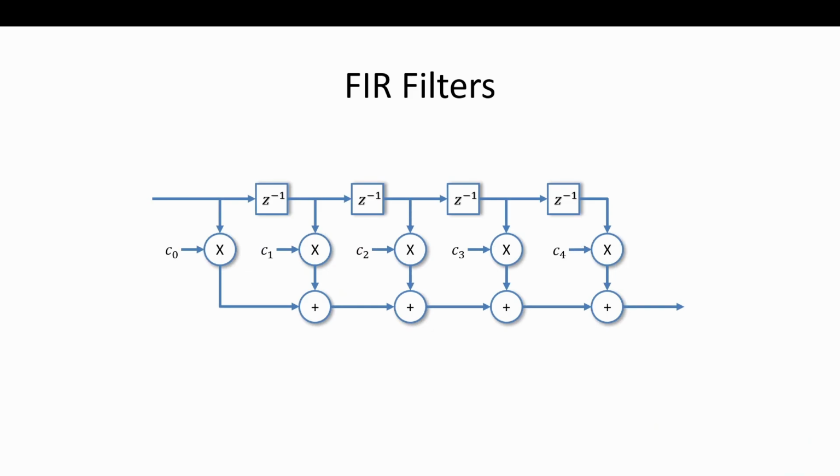So an FIR filter. This is showing you the basic structure of what it is. Just to get everyone on board, those z to the minus ones are a unit sample delay. You're seeing a data path with multipliers at delayed moments and an accumulator at the bottom denoted by those additions. So it's a delay, add, and multiply. It's pretty amazing what you can do in DSP with just those three elements, delay, add, and multiply, in exotic ways. And with FIR filters, we're talking about Finite Impulse Response filters.